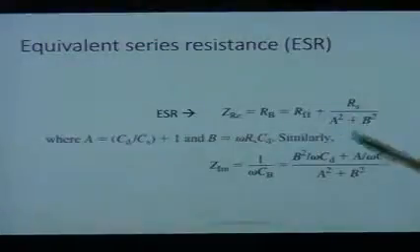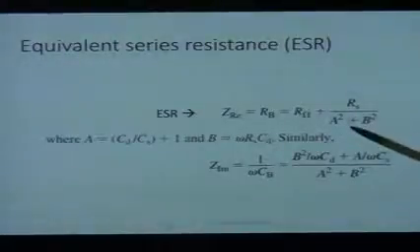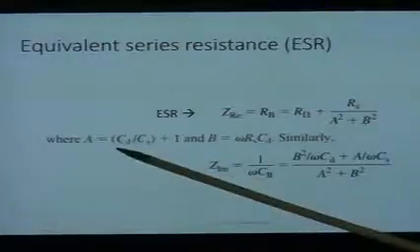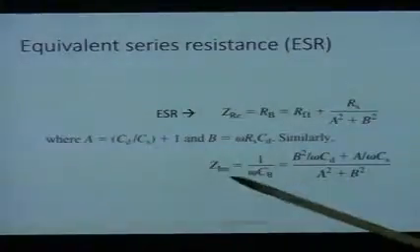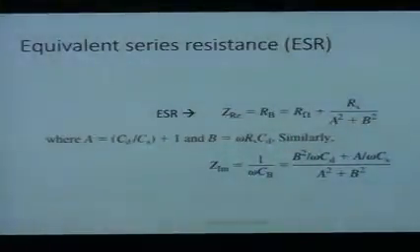Okay? The series resistance in the pseudocapacitive term, divided by our different capacitances that we had, double layer capacitance, pseudocapacitance here, and the B term as well that depends on those, okay? So you can interpret this equivalent series resistance in terms of the Randles circuit as well. So that's what I'm trying to convey here. The imaginary term, again with that overall capacitive reactance is shown here, but usually this is something that is done to really pull out the equivalent series resistance, okay?